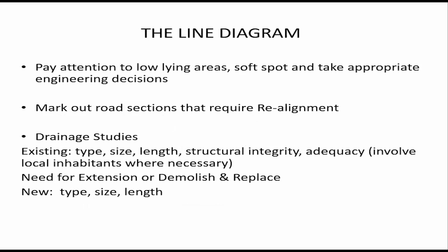And then you need to mark out road sections that require realignment. Sometimes you may see that there is a sharp curve which needs to be realigned. So you have to realign. Or you've seen that there is some rock outcrop around there, which will be expensive to explode. So you may want to do realignment.